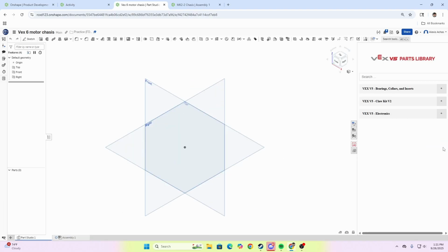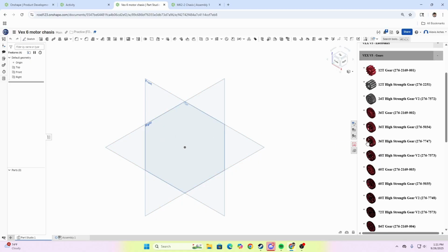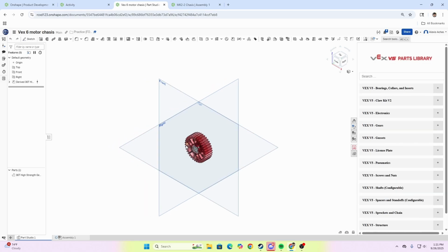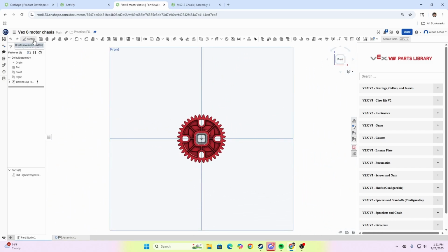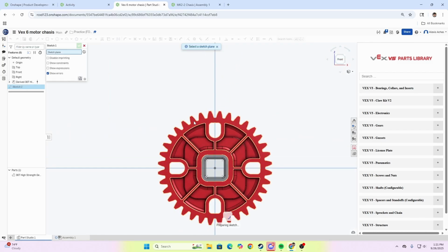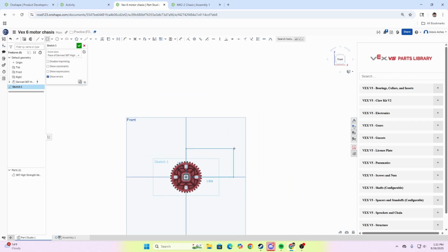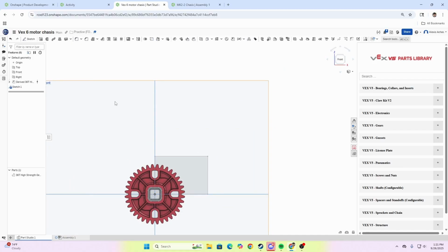And then you can get a gear or any part and insert it in the Part Studio. And this is very powerful. So once it's inserted, right here, ta-da, you guys can modify it right here. So here's what I mean by modify. I'm going to select this plane and then I'm going to select this rectangle. Say we're making a system where we don't really need a certain part of the gear, we only need 3/4 of the gear.